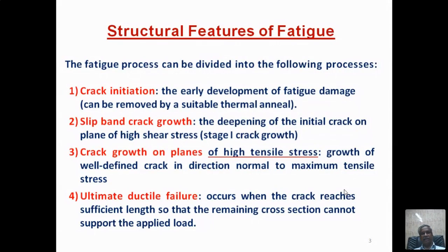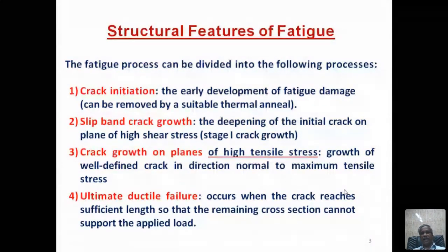The non-destructive testing methods available today can detect up to micron-sized defects or near nano-sized defects, using techniques like radiography or ultrasonic testing. If it is at the atomic level, it is difficult to detect by radiography or ultrasonic testing. Once the crack initiates from some nucleus, it will grow, because the component is subjected to repeated fluctuating load, which drives the crack to grow further.